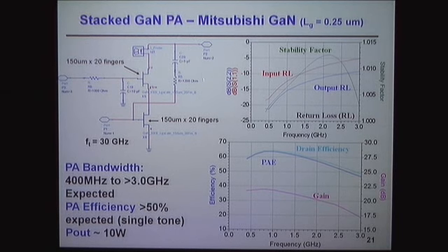Basically, what you're looking at is a feedback technique for controlling what would often be the Miller capacitance of the device, because you would see gate to drain, where you can see, first of all, you put 2 in series, so you get less. And then with the resistive feedback, what that does is that equalizes particularly the S parameters over a very, very wide frequency range. It does reduce the gain, but that's why you stack 2 in series, because you get the gain back. Okay.